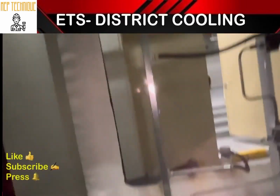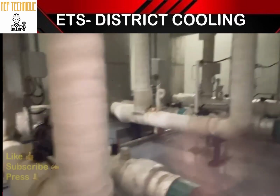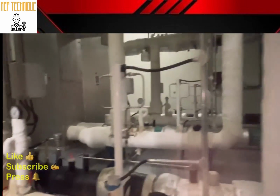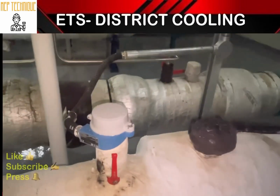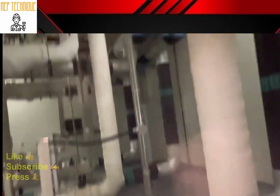Now we are moving to the secondary circuit, which is connected to our building's units like FCU, AHU and FHU. This is the chilled water supply. There is a temperature gauge, pressure gauge, and this is the DPT, differential pressure transmitter, which is monitored by the PLC.